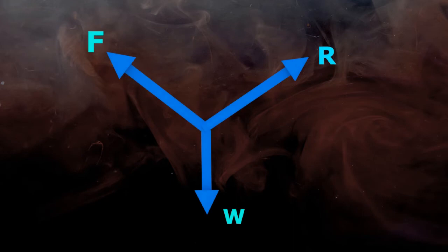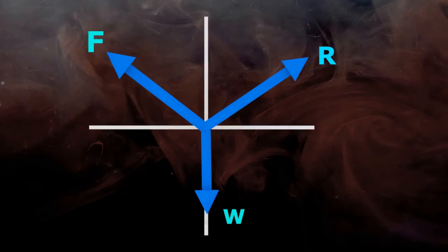Tails of all the forces are meeting at center. So now let's find out magnitude of R and F. As this is the problem of equilibrium, either Lami's theorem or equilibrium conditions can be used to solve the problem. Both methods give same result. We will find out forces using Lami's theorem. For this method, the very first step is to find out angles between adjacent forces.